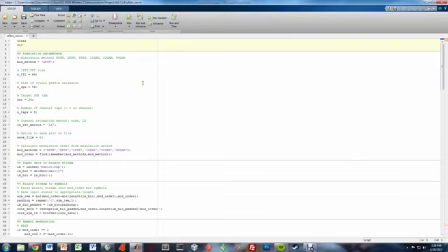This is the main OFDM simulation script. The first thing we do is input different parameters for the simulation. So here we're using QPSK as the modulation method, an FFT size of 64, a 16-length cyclic prefix extension. We are specifying a target SNR of 20 dB, telling the channel that it has 8 taps, and we're going to use least squares as the estimation method. This allows you to save the plots at the end to a specific file.